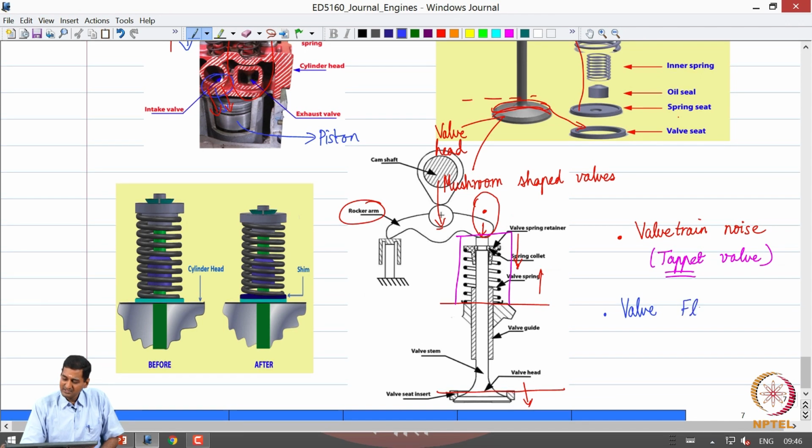Okay. So what is valve float? That is, the valve will seem to be floating, that is, it never closes completely and never opens completely, because by the time it opens completely, the command has reversed to closing it, but the time it starts to close, the next cycle would have started and it would have been commanded to open. So that is going to be a challenge, right.